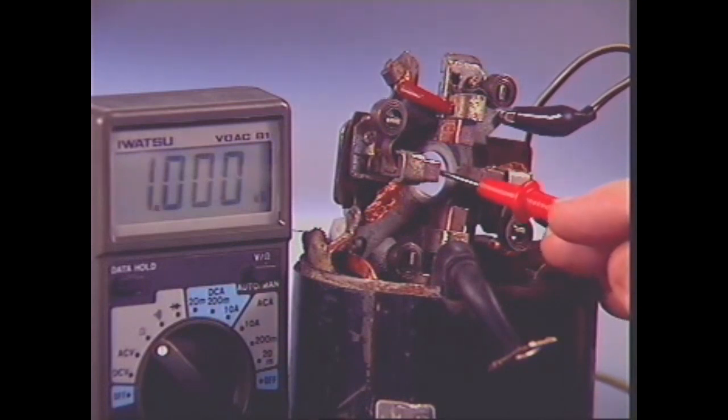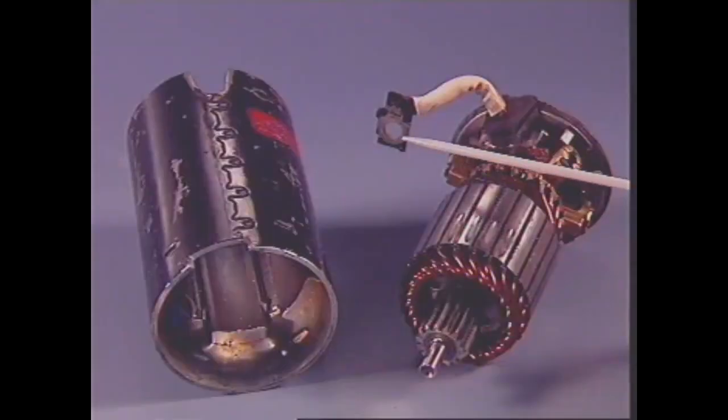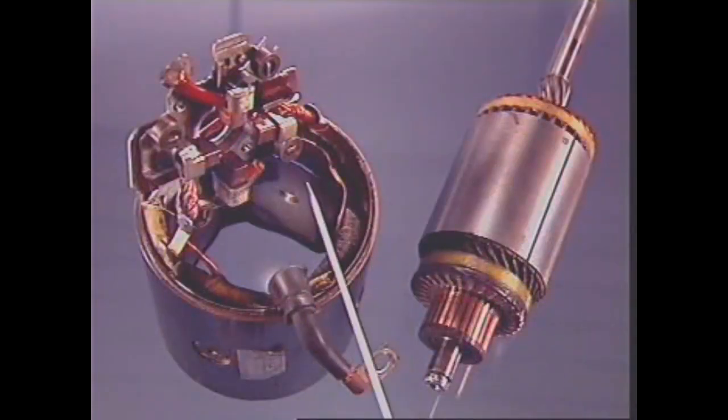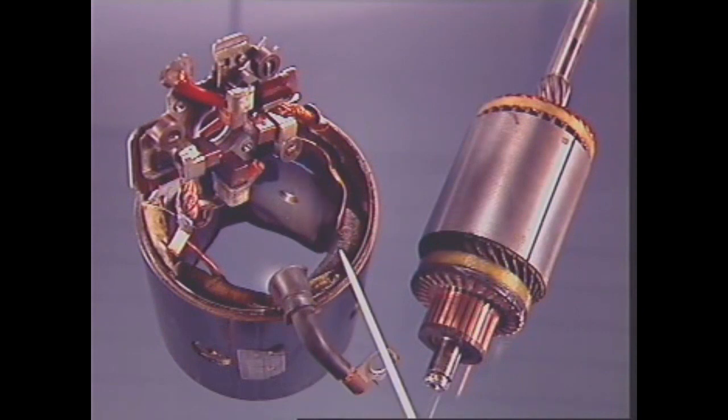The other half are insulated from the end frame and connected to the positive battery terminal via the main starter solenoid input terminal. This can be a direct connection in the case of a permanent magnet type starter, or indirectly via the electromagnetic field poles of a series wound motor.